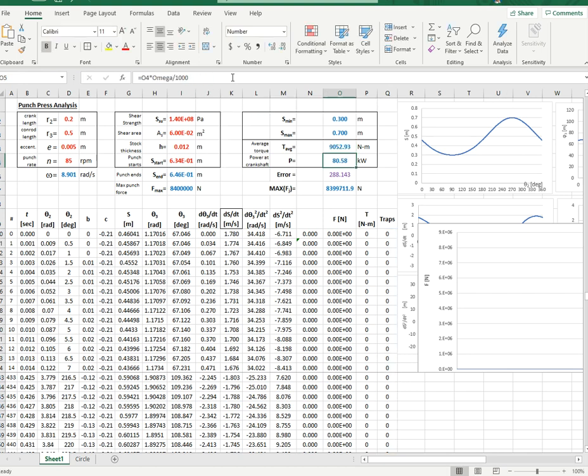For this, see the homework and the problems that I did on camera for sizing flywheels. So this is going to give me the area under the curve, that is total energy per one cycle divided by duration of the cycle. This gives you the average torque. Okay, so you have the average torque. If you know omega, you can calculate the power. So average torque times omega, that's giving you the power of the crankshaft.